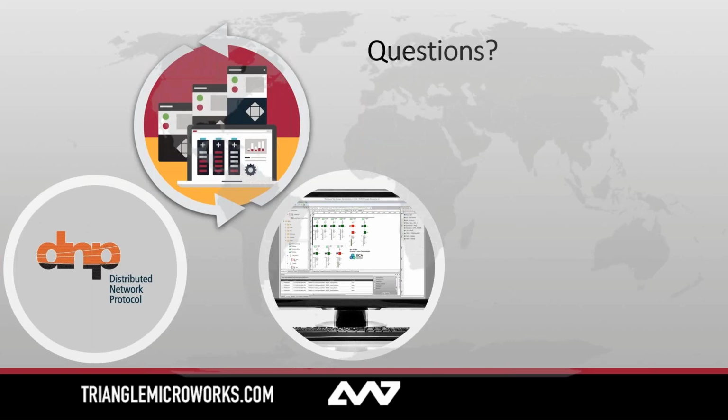Can we check interlocks between substation elements in IEC 61850 that we are normally doing using DCU? Yeah, so that's why I added the two switches on the side of the breakers. We actually have some interlocking code written into the very first finalized workspace I showed you. So interlocking can absolutely be monitored and tested there as well. It all just comes down to what kind of behavior and scripting you have behind your simulation.